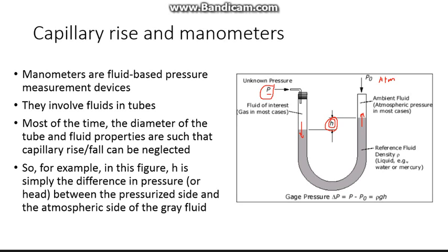So it's generally just taken for granted in these types of problems with manometers, unless it says so, or there's a very thin radius on the capillary tubing. You can kind of ignore capillary rise and just go with the distance being caused by the pressure.